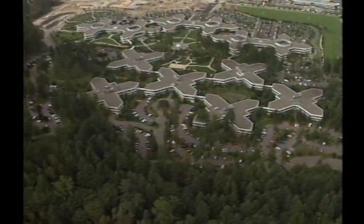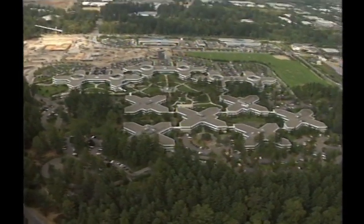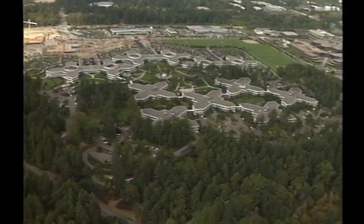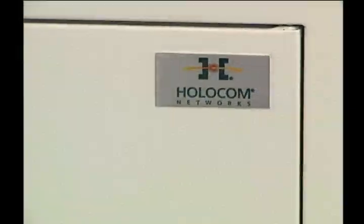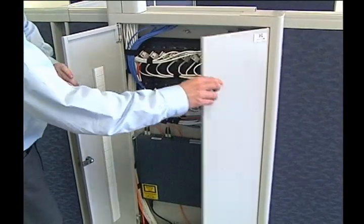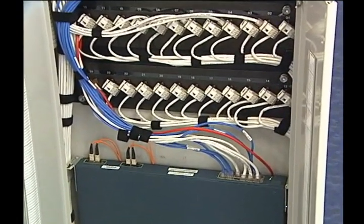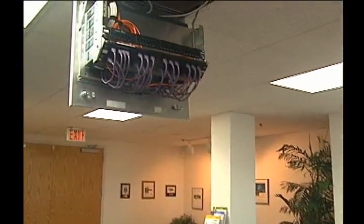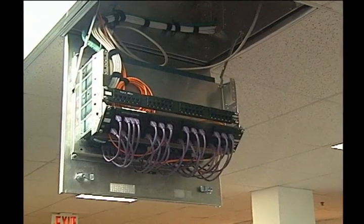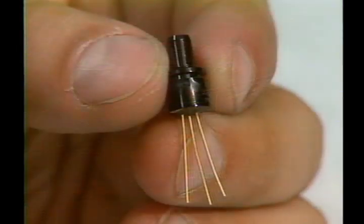In the early 2000s, increasing bandwidth demands were driving the need for low-cost gigabit and 10 gigabit connectivity in local area networks, storage area networks, central office, internet, and data centers. Multimode fiber traditionally provided the lowest cost for short-reach, short-wavelength systems operating into the hundreds of megabits per second by allowing lower transceiver, connector, and cable termination costs. However, LED-based networks could not support gigabit per second data rates, requiring new low-cost lasers for multimode fibers. The availability of low-cost lasers in the form of vertical cavity surface emitting lasers, or VCSELs, provided a great incentive for system operators to increase the performance of their multimode networks.